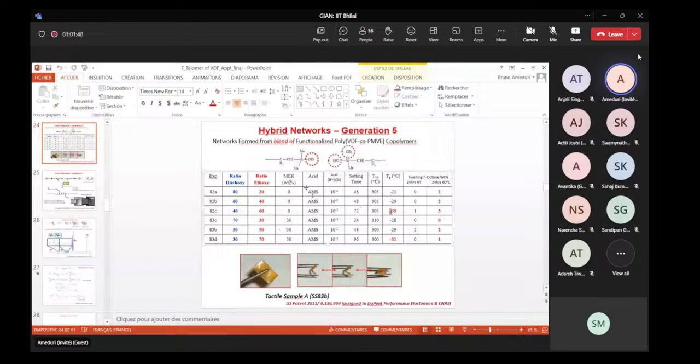However, the swelling was very good, 24 hours at room temperature, negligible, and when you heat it up in octane for 24 hours, it was good, lower than the threshold. So we could prepare some monoliths, and they were very soft, as you can see, because of the Tg, but let's say not as satisfactory as we expected.